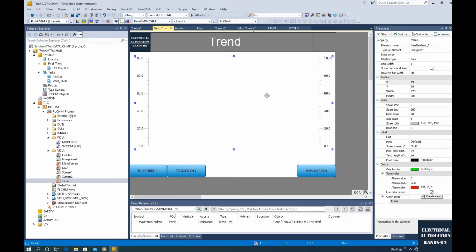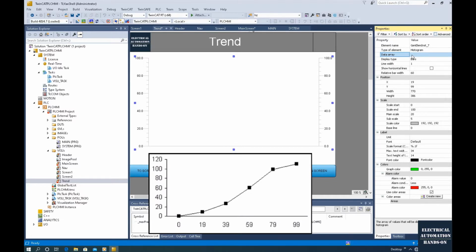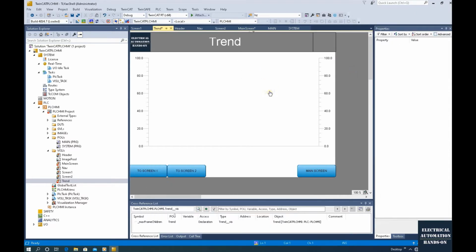So the key data we can connect to this component is here, the data array. Keep in mind, this is one data array rather than one data only. That data array could have 500 data inside, and each data is related to one pixel in this histogram. Those 500 dots, the pixels, combine together to show as a curve. So we temporarily park here. Let's shift to the PLC side. We need to program that data array. This is the key area we need to show in this video.